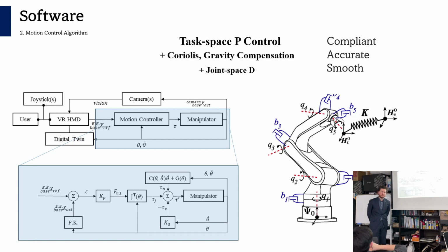What I mean is that if you move your system very slowly, then you might be able to achieve your goal trajectory of the end effector. But if you increase your speed, then those B1, B2, B3, which are tuned separately, will give you a different response from the motors. Therefore, the entire trajectory can be corrupted, and that would be the case if I was controlling the manipulator's end effector in this position method.